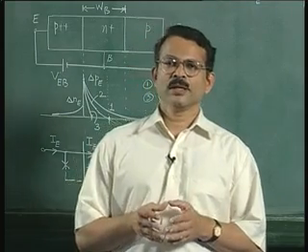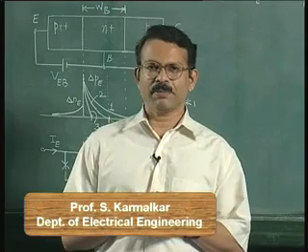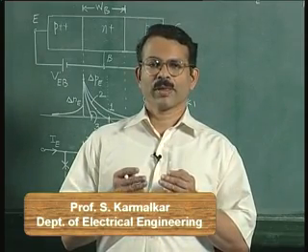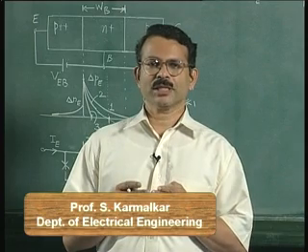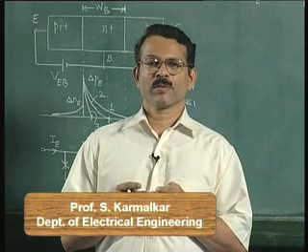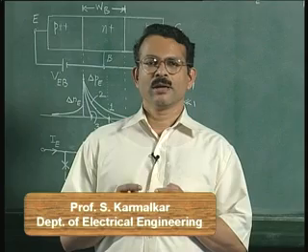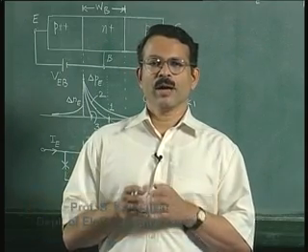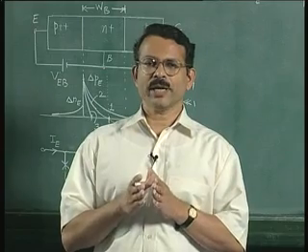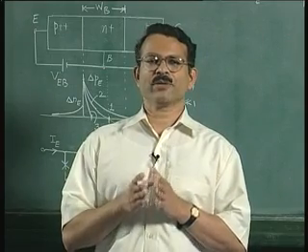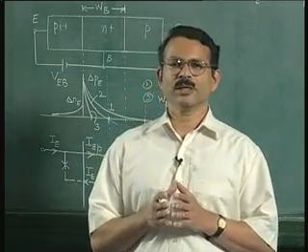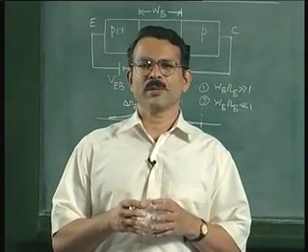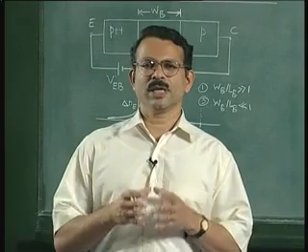Now based on the simple PN junction theory that we have developed, which says that the currents at the junction are because of diffusion of minority carriers, and therefore at the junction depletion region boundary the current can be estimated from the slope of the excess carrier distribution, we can get the variations in the various current components as the base width is reduced in our thought experiment.